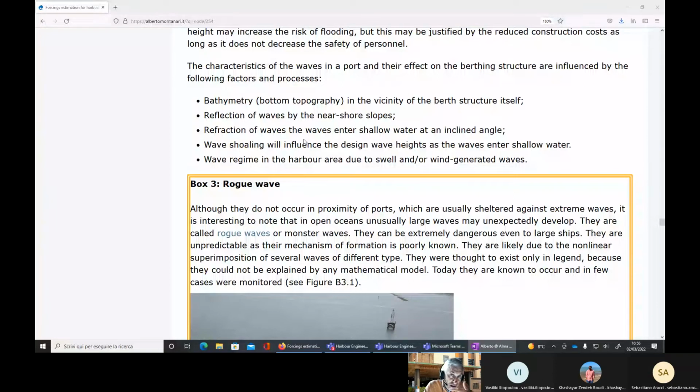Because the mooring lines are always elastic. We want them to be elastic because in this way they are more resistant. On the other hand, if you think of anchoring a ship with elastic mooring lines, when you get this up and down movement, of course the elasticity of the mooring lines contributes to the movement. And as I said, there is a characteristic frequency of this up and down movement of the ship. And if the characteristic frequency is coincident, very close to the frequency of the waves, you can get resonance. I think you know what resonance is.